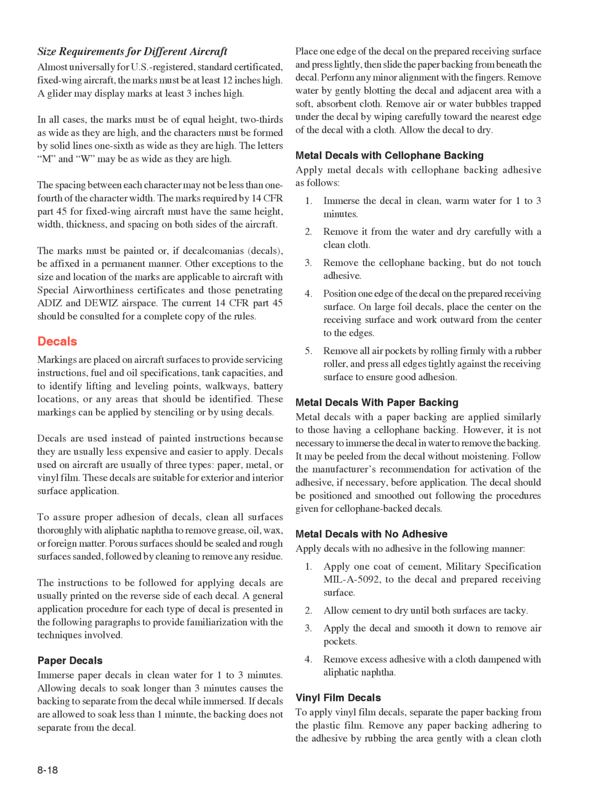Metal decals with cellophane backing. Apply metal decals with cellophane backing adhesive as follows: 1. Immerse the decal in clean, warm water for 1 to 3 minutes. 2. Remove it from the water and dry carefully with a clean cloth. 3. Remove the cellophane backing, but do not touch adhesive. 4. Position one edge of the decal on the prepared receiving surface.